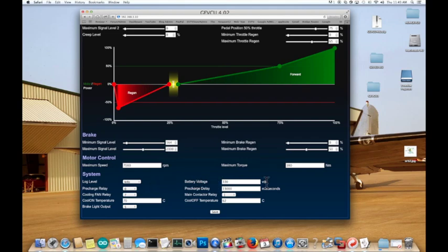Battery voltage, 330 volts DC. I've got 160 amp hour cells in the thing. When I get done charging it, it'll be about 334 volts. Right after charging it, it might be 350 volts. But if I get in the car and turn the ignition key on and back it out of the shop and start down the road, it's going to drop below 330 quite quickly.